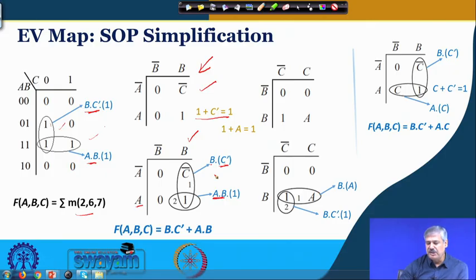For the same truth table with the entered variable map considering A, we shall see this is the corresponding map. For minimization, again with 1 we get B and C prime, ANDed with 1, and for A we can consider 1 as 1 plus A, without any difference in meaning, and that will generate B, and the entered variable is A. So, AB.